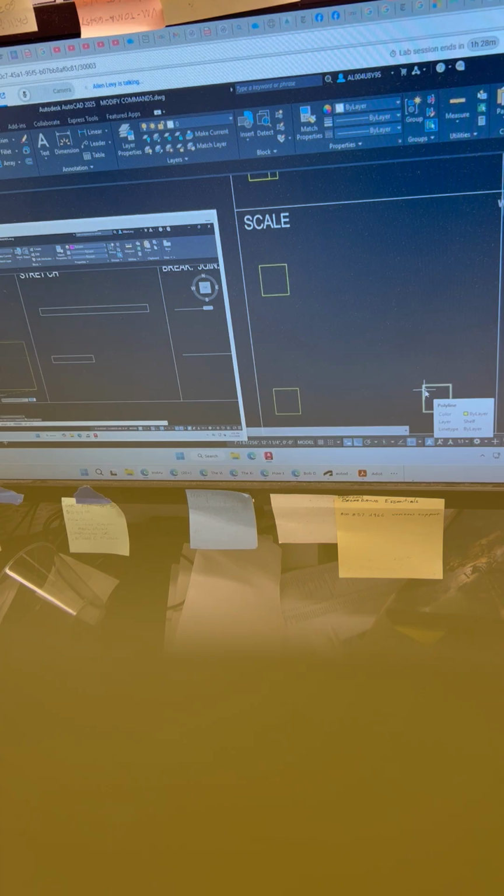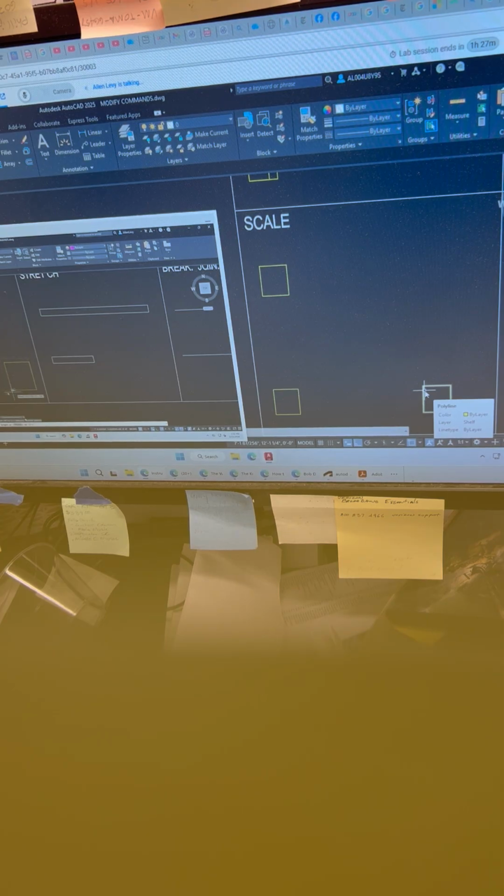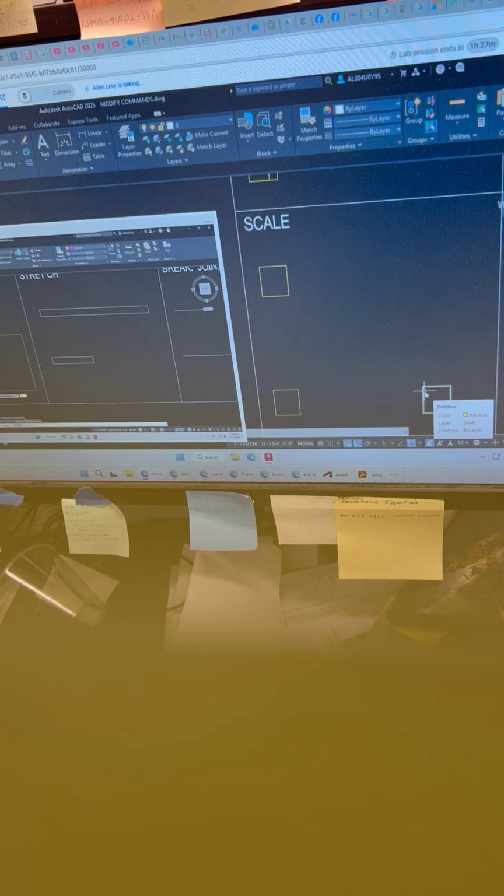All right, now when I do that, look how my cursor and my rubber band and so forth, they're all relative to that bottom edge. Now this time, I can put in 3 feet because the first thing that I picked off the object was the reference length.